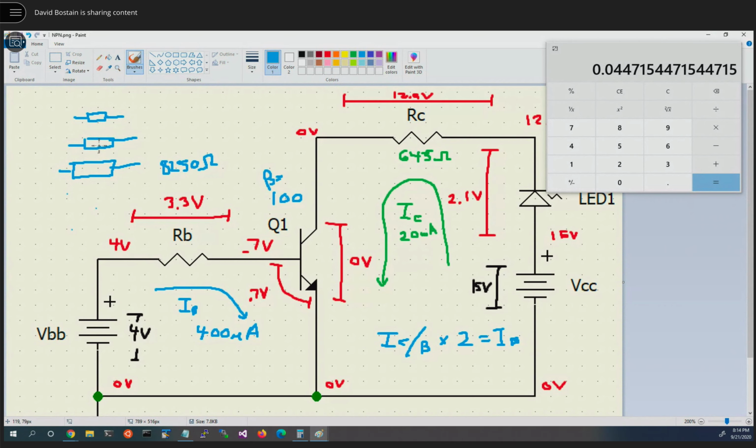That's what's going on. Now, you mix brands and you go get another one, and you just get an arbitrary one out of a box, and it's this size. What wattage is that? You have no idea. So either you have to see the receipt in the box it came in with, which is usually what I do, or you have to make sure you pick one that's nice and fat and put it in a place where there's not much current. I tend to buy things in bulk and leave them in the boxes until I use them. And when I give them out to students, I tell you exactly what it is, and you should put it in an envelope or something that is labeled so you can find it again.